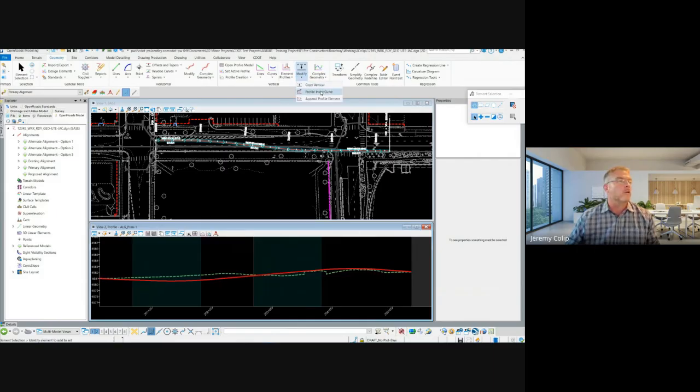The other method you can do as well, just like we showed in the horizontal profile, insert curve, is another way that you can just add those in, put in the radius, what you want, and checking your K values and your design criteria through it that way. So this is really creating that. It's more by PI and inserting curve.